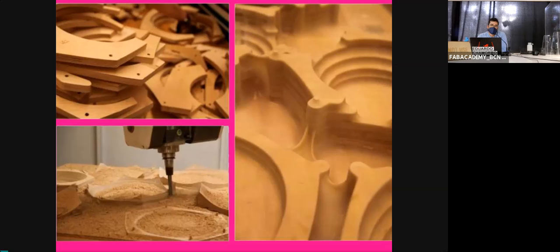Actually, it's widely used, for example, in the aerospace industry to produce 3D printed stainless steel parts or aluminum parts, but then those parts are milled with a CNC to get the tolerance that you require, because the outputs of these 3D printers are not as accurate as the outputs that you can produce with a CNC milling machine. For example, car engines are made by foundry of aluminum, a massive block of aluminum, and then they are milled or turned with CNC machines to get the tolerance that you need for the inside mechanical parts.